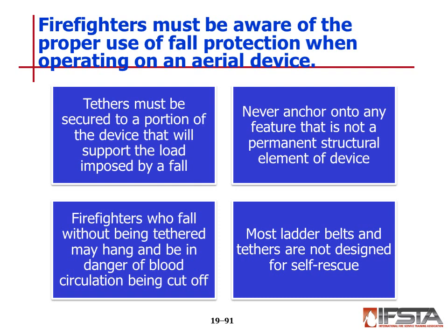If you fall while tethered, you may hang without the ability to climb back onto the device. People can only hang briefly before blood circulation is cut off and they begin to have issues. Most ladder belts and tethers are not designed for self-rescue. Prepare a plan that will ensure personnel who become hung from safety ladder belts and tethers are rescued immediately. Never operate the ladder or platform device while alone.